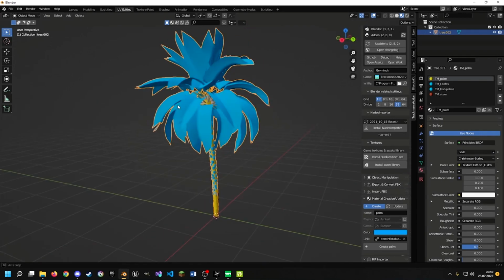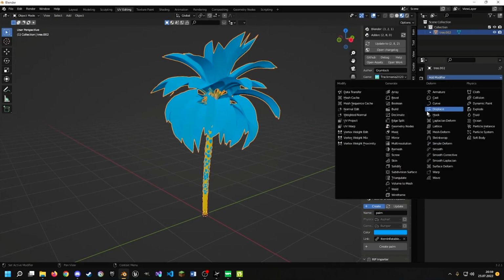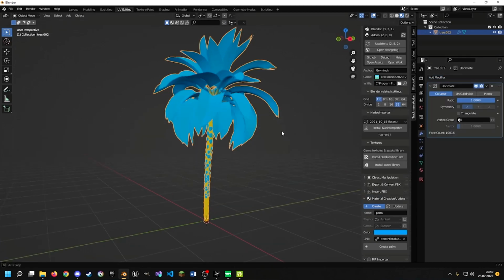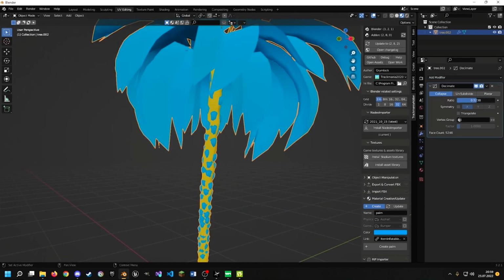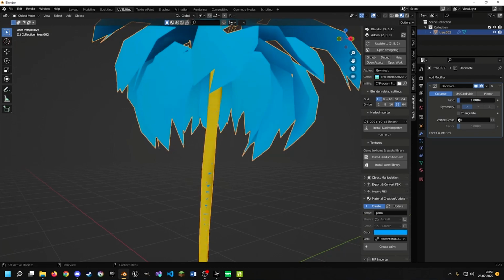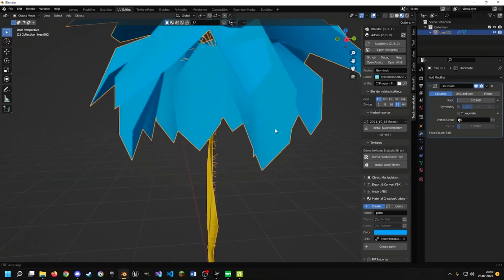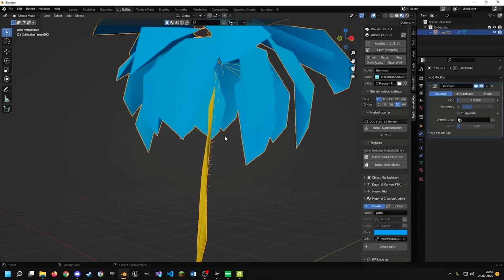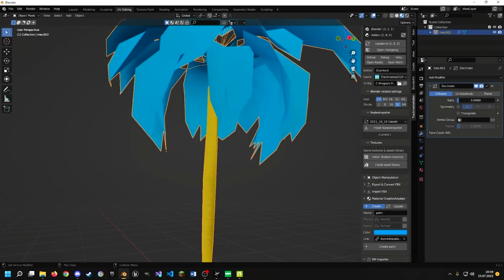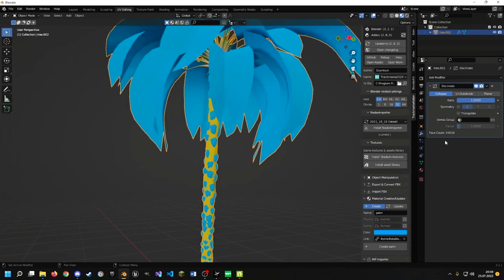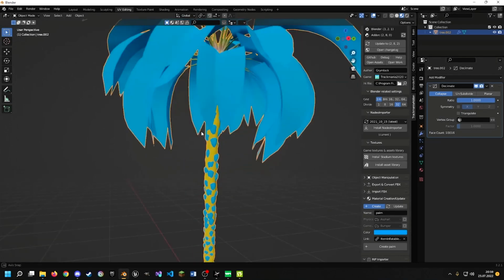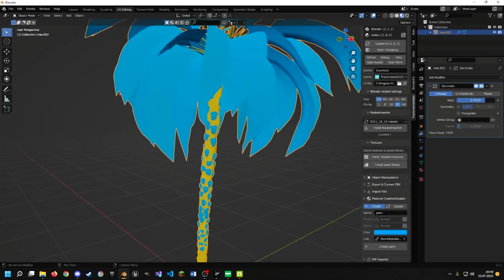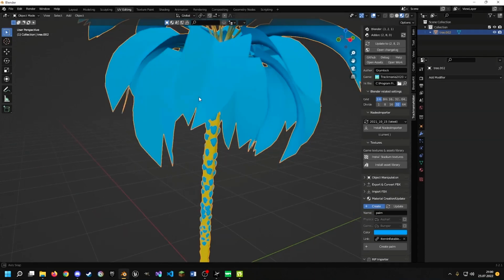And I also got asked how to reduce a model or how to reduce the size of a model. You can use the decimate option. It tries to decimate an object, you can see this, to a really low poly form. This doesn't look good, obviously, but it's just for showcase purposes right now. 10K is quite large for a tree, so I recommend optimizing it a bit. But I just keep it like this for now.